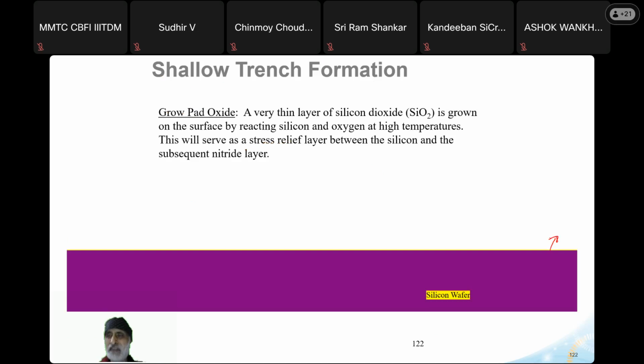It goes in a furnace under oxygen, and the flow rate of oxygen is controlled. There can be dry and wet oxidation, and they are different. The kind of oxide, SiO2, is actually SiXOY: how many silicon atoms and how many oxygen atoms make a bond. Depending on the quality of SiO2, the temperature, pressure, and other conditions vary, which we study in detail in the topic of oxidation.